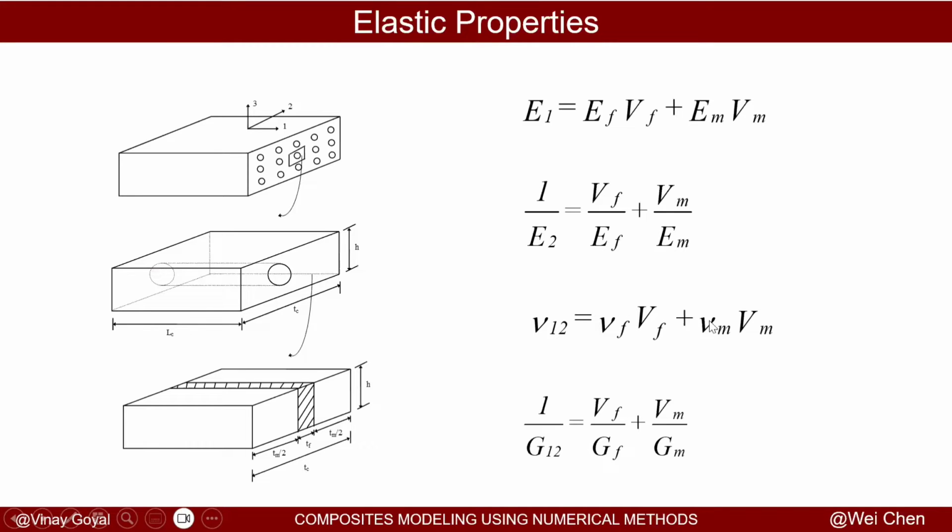But you can predict that indirectly, because if you know the fiber volume fraction and the matrix volume fraction, you can then estimate this Poisson ratio. It won't be perfect, but it is an estimate, and it is possible to do that. In a very similar manner, we can calculate the shear modulus, which is a prediction as well. Using information on the fiber volume fraction, the matrix volume fraction, the shear modulus of the fiber, and the shear modulus of the matrix, I can then estimate this shear modulus. That information is not completely sufficient, and it may not be perfect, but it is a good start.